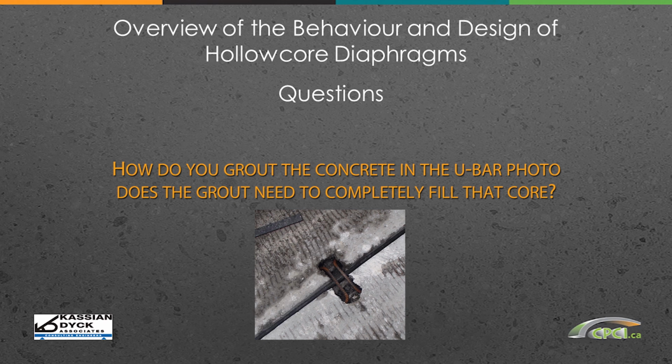for that particular connection. And again, it's up to the precast engineers that are designing those, how they're designing it, if they're looking at it as a shear through the bar or tension friction, and where that load is going and how it's working as a connection, and does it have sufficient capacity. So certainly would want to fill it fully in that region of the U-bar, and again, that's all based on the engineer's design.